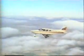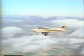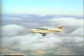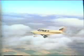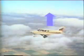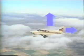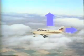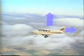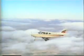A better way to predict performance is to simplify the analysis of aerodynamic force by dividing it into two components: lift, which is perpendicular to the relative wind, and drag, which acts parallel to the relative wind. With this goal in mind, let's take a closer look at lift and how total lift and, consequently, aircraft performance are determined.